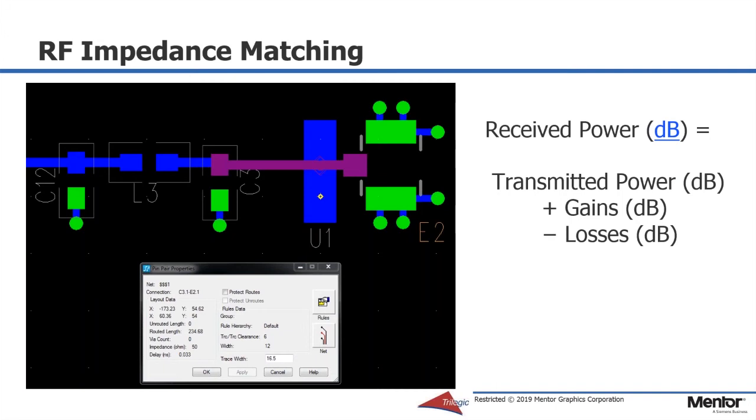So all we have to do is to select the pin pair option, which is by selecting the trace, and then right-clicking and showing properties, which we see down below here. On the next slide, you can see an arrow pointing to the impedance, which is 50 ohms. Now, there are many electrical and physical properties that affect impedance. One is the thickness of the dielectric of the circuit board, which you can enter into PADS. Another is the trace width. Another is the thickness of the circuit board, and all of the electromagnetics around the trace.